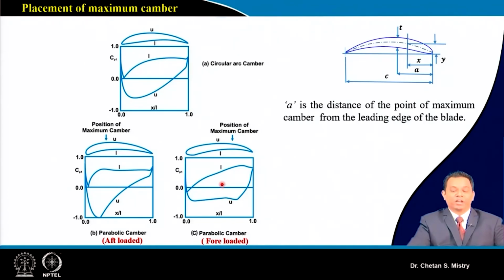That means, based on the shape of my aerofoil we get the CP distribution; by using a numerical tool, they take this available CP distribution and then develop a new kind of aerofoil based on it. That's what is called inverse design.